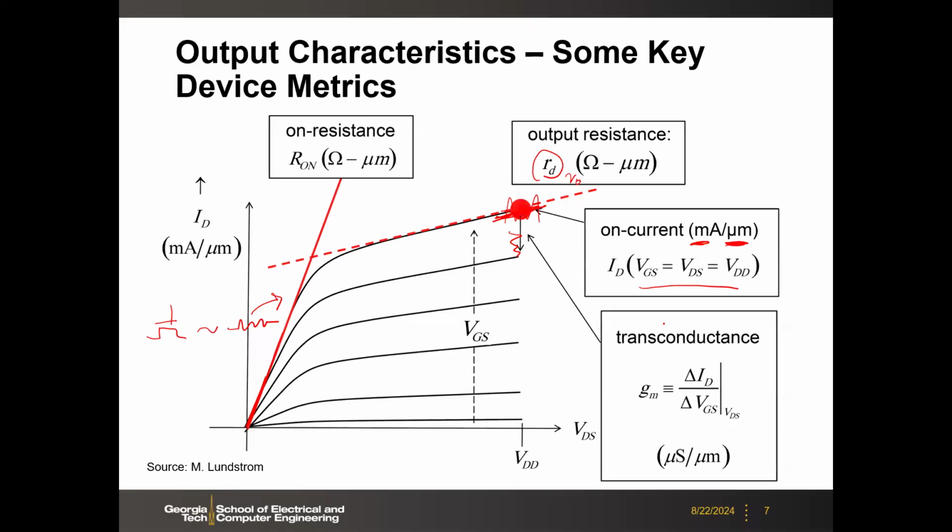And then the transconductance is a gradient, let's say delta ID over delta VG. So by varying the gate voltage, how much drain current change you may get. This is defined as the GM, transconductance, which is also important for analog circuit design. So those are just some basic stuff. I assume you learned that through your undergrad study already.